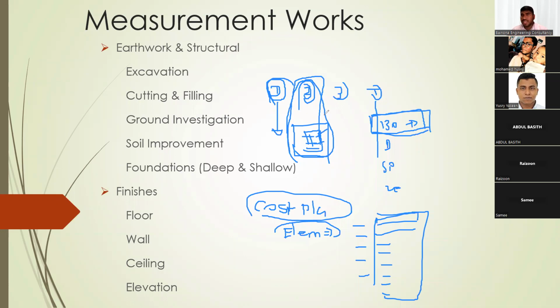So one of the quantity surveyor's duties here is to give quantities to the cost planner. Then in the third stage, the schematic design stage or the detailed design stage, the design will be revised, because concept design is not the same as schematic design. The design is developed a little bit in the schematic design, and further developed in the detailed design. From design to design, the quantity surveyor's job is to quantify the work and give it to the cost planner. Once the cost planner has made the project match the client's budget, the cost planner will leave from that stage.